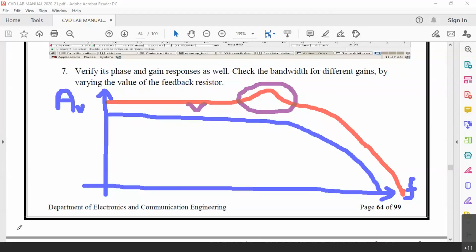So that is where Miller had modeled a transistor, because if you remember the BJT common emitter amplifier, emitter is common to base and collector, and between base and collector normally we ignore the capacitance, that junction capacitance or the collector to base parasitic capacitance.